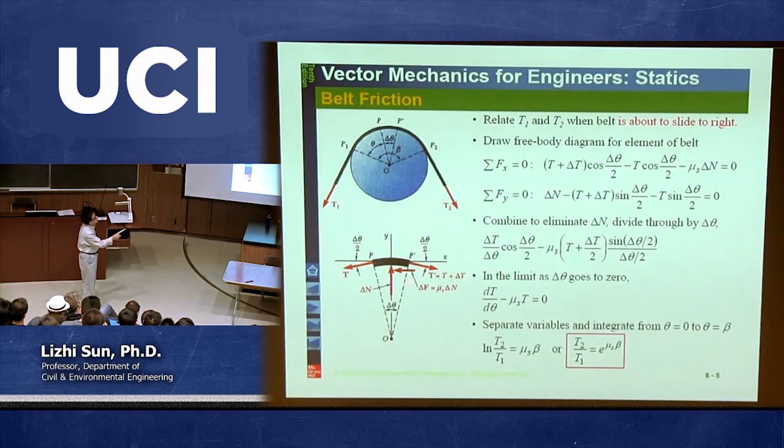So this is what we call the free body diagram. What you need to do is to collect all the forces in the x direction and set equal to 0. You need to collect all the forces in the y direction and set equal to 0. That's a typical static equation, right? You may say, what is the third equation, which is the moment equation?